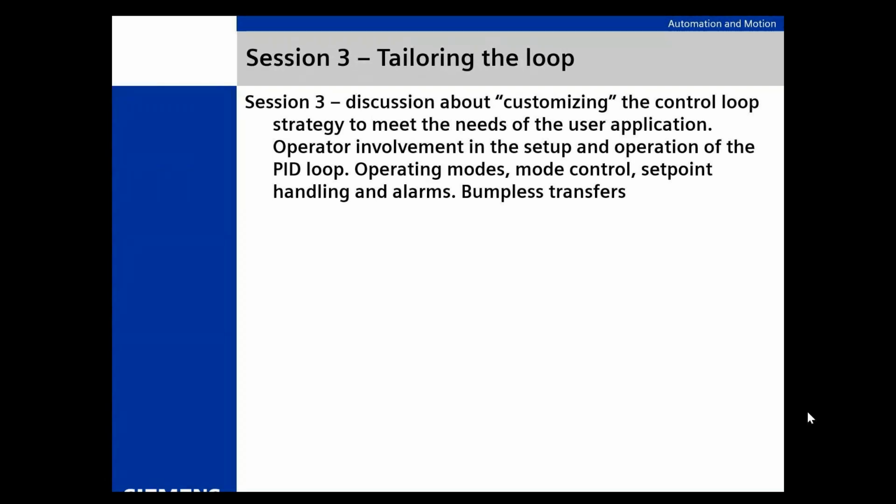Okay. But remember, when you're tuning a loop of any control, things are tied together. I can't speed it up without maybe losing a little resolution. Maybe I want it a little more accurate, but that requires slowing it down. Everything's tied together. I can't change a variable in this PID loop without affecting everything else.